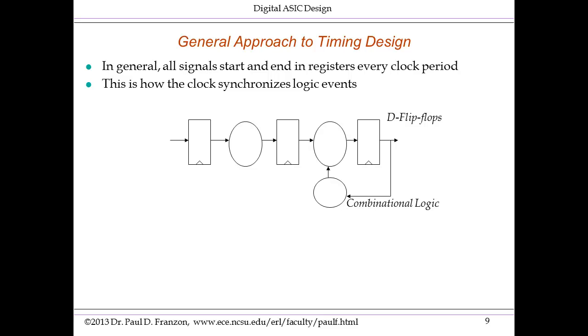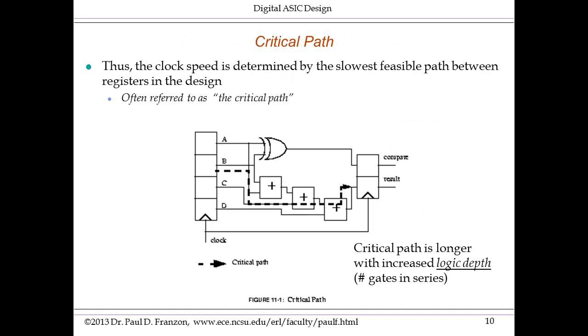By the way, how do you decide what has to go into the flip-flops? In essence, it's quite simple. What information has to be preserved between clock periods to achieve the operation that you want? So within each clock period, all the logic must propagate through a design, through the combinational logic, for all the possible logic paths in a design. And in a modern design, there might be billions of those.